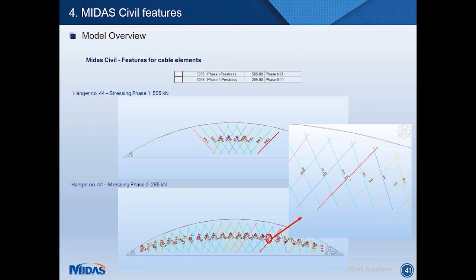In other packages, I would have had to either convert this into an elongation and make sure that the force is coming out, or deactivate this element, the original element, and activate a new element in the same stage on top of it. So I like this feature of MIDAS, and it makes my life much easier.